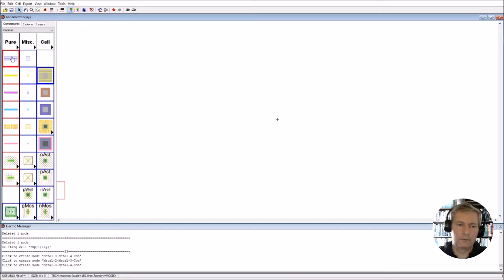First of all, we click on there and it says metal 4. Now we can come down here and this one says metal 3, metal 2, and this one says metal 1. So these are the metal layers. Remember, whenever we ran this up at first, we had an option of choosing the number of metal layers, and we chose 4 metal layers. So the blue one here is metal 1, so that's going to be down at the bottom, if you like, of our sandwich structure. Then we would have a layer of oxide, which is just an insulating layer above the top of that.